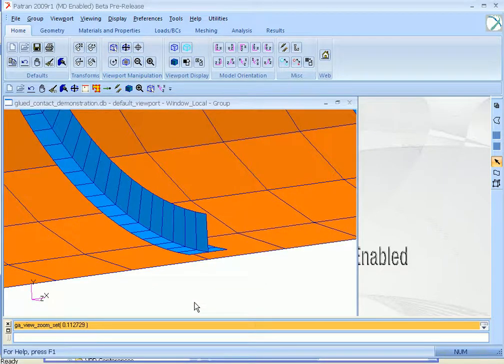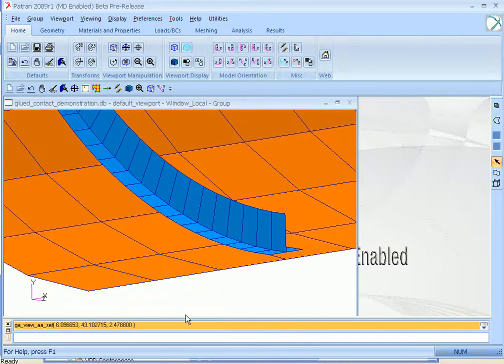You can see we essentially have a mid-surface of two shells, and if these were 3D parts, they would be sitting on top of each other. So we need to pay attention to the curvature because the curved panel is flatter around curvature, and the ribs have a more discretized refinement. So we will need to play with the curvature, which I will demonstrate as we build these contact bodies.